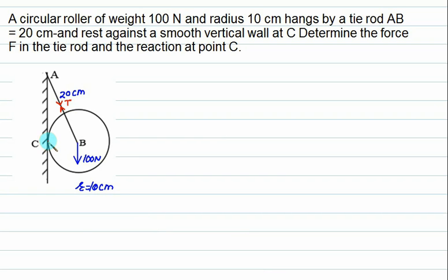Do you have a contact reaction here? So we have one contact reaction and this angle. Can we write down this angle equal to theta? For this right angle triangle, that is cos theta, that is 10 divided by 20. Theta equals 60. Is this fine?